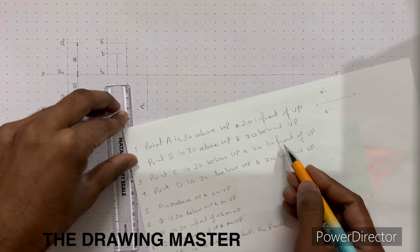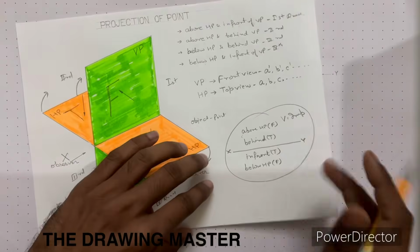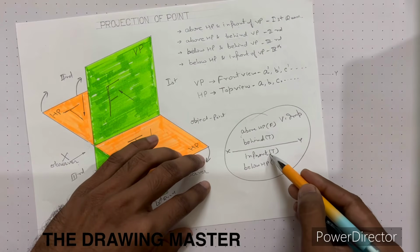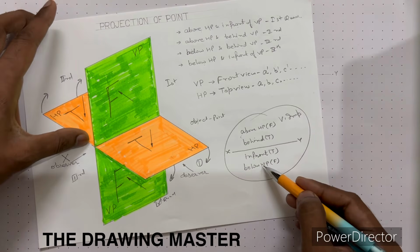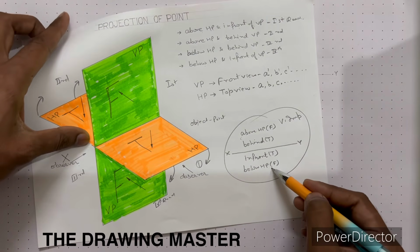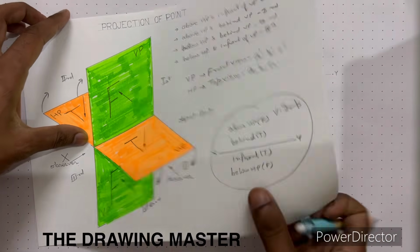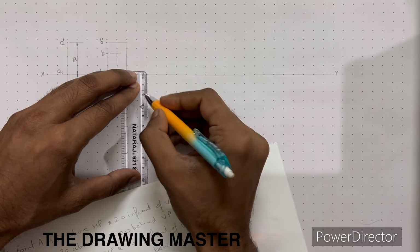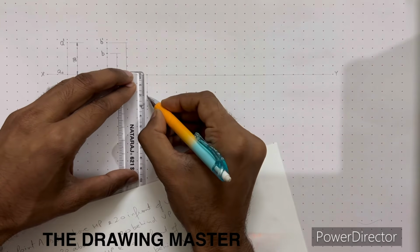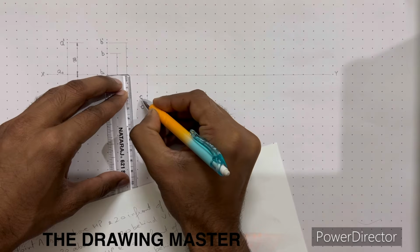And 20 in front of VP. So where are we drawing in front? Let's see this. In front means below the reference line and it is top view. 30 below HP means below the reference line and it is front view. In front is also down to the reference line. This one is the top view of the point.